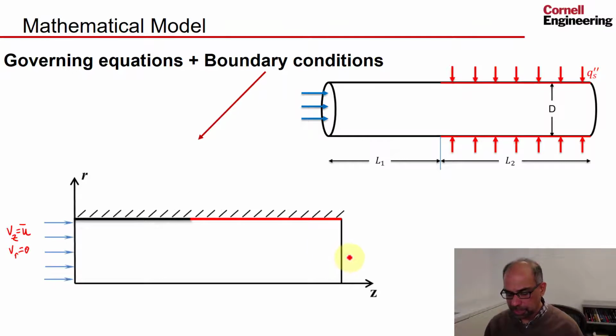And where the flow is coming out, we will put a pressure boundary condition, and we will put it as 1 atmosphere. It turns out that the actual value is not important because a pressure gradient is what determines the temperature and velocity field. So if you change this value, you'll just change the pressure field by a constant. So typically where the flow goes out, you put the pressure boundary condition. Where the flow comes in, you put the velocity boundary condition.